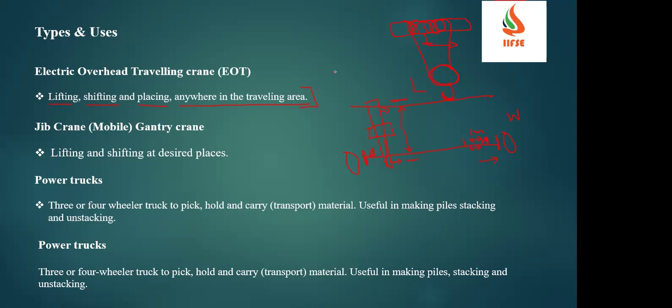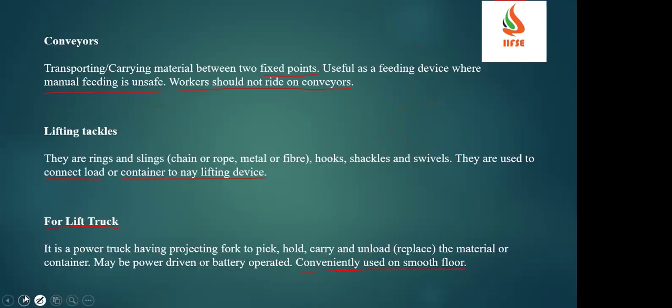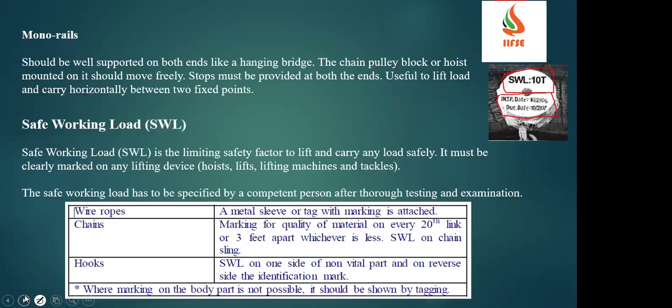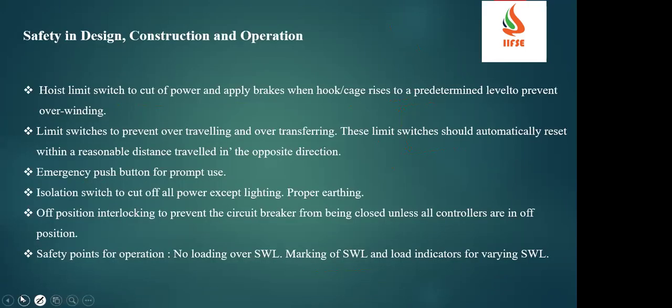For this kind of EOT crane, we should have emergency push buttons, and we should have isolation switches to cut off the overall supply.